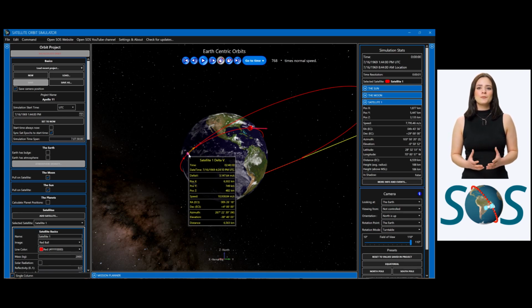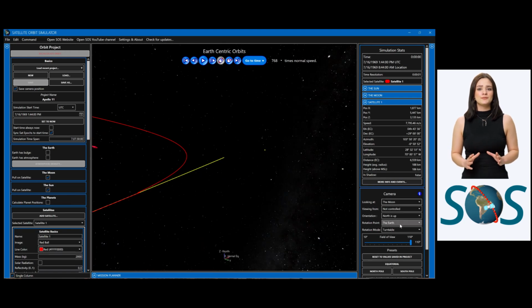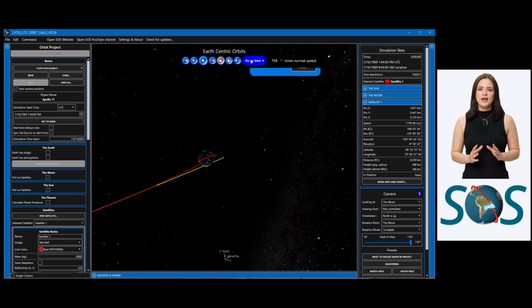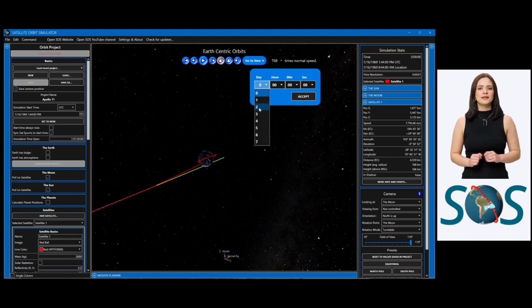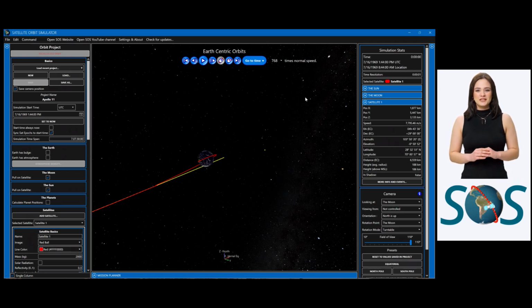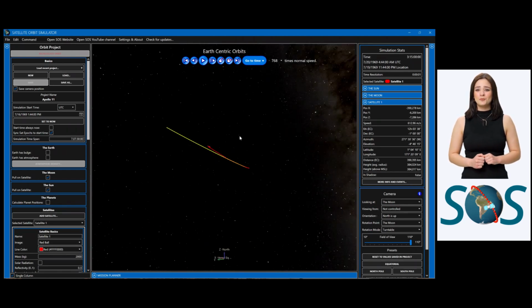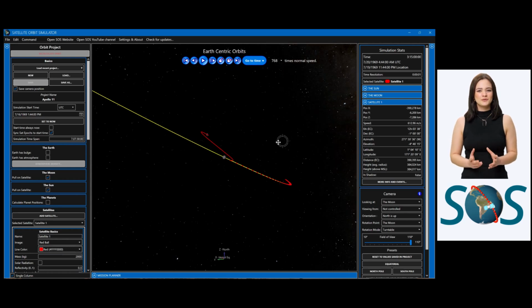UTC, the Hohmann transfer orbit was initiated to enter a translunar trajectory that intersects with the Moon. This occurred on the opposite side of Earth relative to where the spacecraft would approach the Moon. The delta V, or change in velocity, required was 3,147 meters per second, which required a significant amount of fuel.